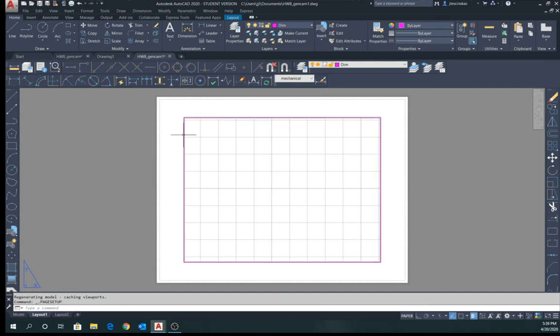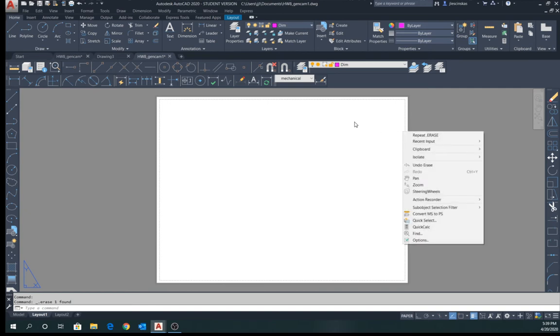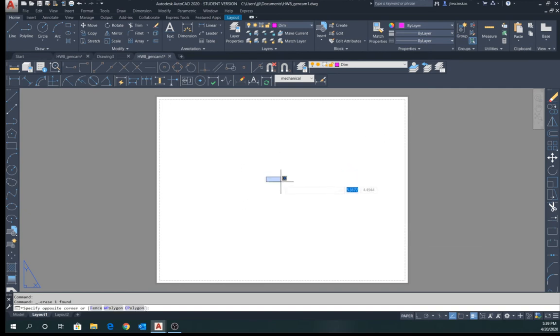The next thing we're going to do, and again, this is the viewport. Click on this viewport, and for now, just go ahead and delete it. So it's going to be gone. Now, these dotted lines here on the outside, this is the actual print area. If you recall, we just set up the print device to be an Adobe PDF. So essentially, the print area is the whole page, except for the very, very slight outside margin. If we set an actual printer, these dotted lines would be